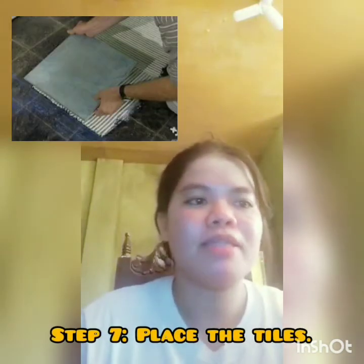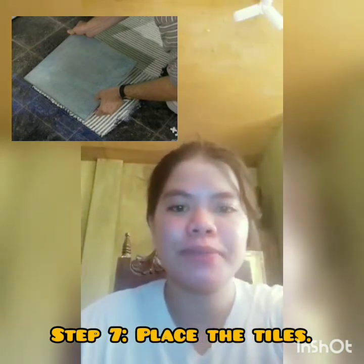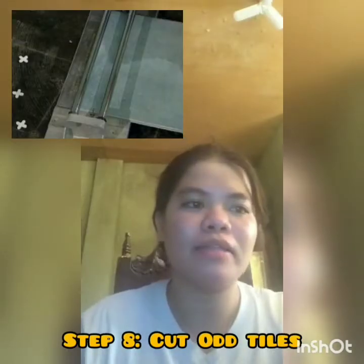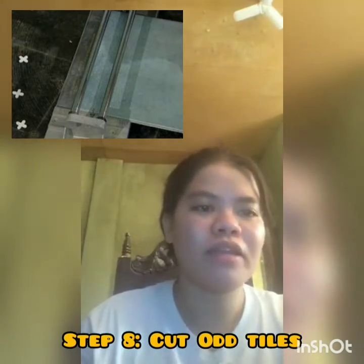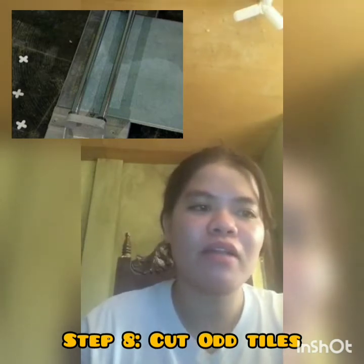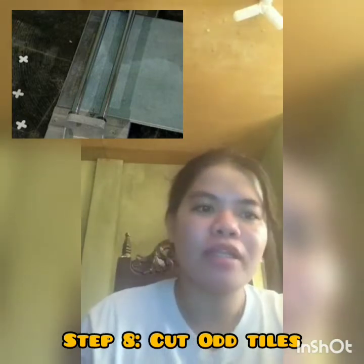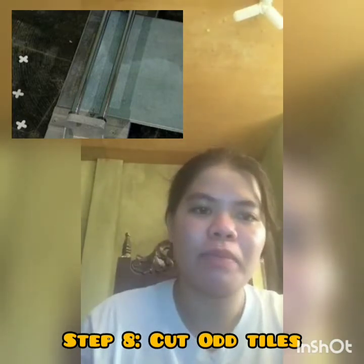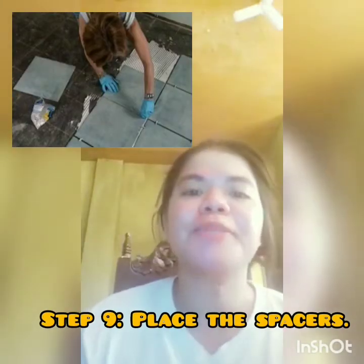Step 7. Place the tiles. Put the tiles in place. Step 8. Cut odd tiles. When you get to a wall where a standard tile will not fit, mark and make cuts with a standard tile cutter. If you don't use a tile cutter, mark the tile and have a tile supplier cut it prior to installation. 9. Place the spacer.